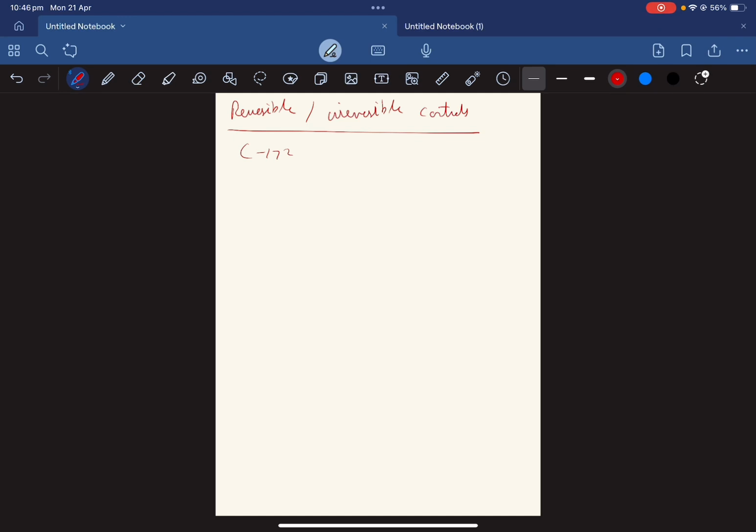So when you move the elevator from outside the aircraft, so let's say this is your elevator, right? If you move it down, if you move it up, and of course definitely the control column, if you're moving it up and down, the control column will move forward and backward, right? So if this is happening, then you call it reversible controls. That means the controls in which aerodynamic loads from outside the cockpit control the inside too. So this is called reversible, and the opposite would be irreversible controls. Controls in which aerodynamic loads from outside cannot move the cockpit controls inside. That will be reversible and irreversible controls.